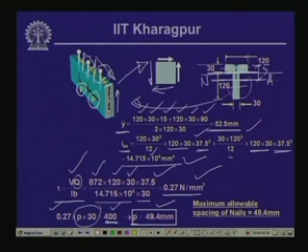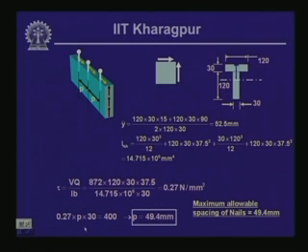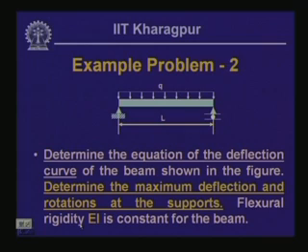So, that means these nails can be spaced at a maximum distance of 49.4 millimeter. We can keep a lower value than 49.4 millimeter, but we cannot exceed it. That is the maximum spacing of the nails that can be provided so that the shear force in the nail does not exceed 400 Newton. If we go beyond that, the shear capacity of the bolt will be exceeded, the bolt will not be able to withstand it, and the whole section will fail. So, this is the spacing of the nails to be provided so that the member becomes safe. Well, that was the problem for the shear stress.